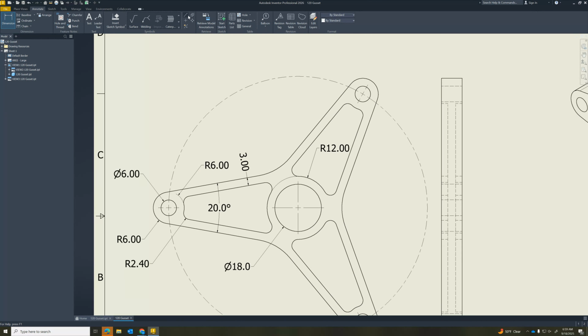And a way to do that is we can get a line here and then a line here, and then give the angle between those 2 lines. And so to create a line, we can click here, center line, click this point here, go over, click this point here, and then right click and go create. And then I can do that again, click here, right click create, and then go to dimension, click this line here, click this line here, and then we can go out and give that angle at 120 degrees. Again, you may want to position it so it's not overlaying different numbers or different lines.